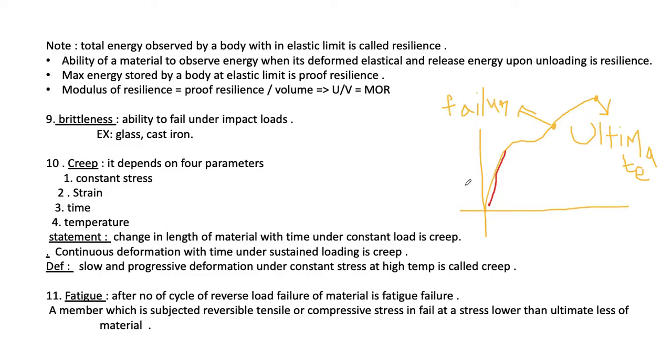Another definition for this: the maximum energy stored by a body at the elastic limit is known as proof resilience, which is nothing but the maximum energy stored in a body at the elastic limit. Modulus of resilience is equal to proof resilience by volume.